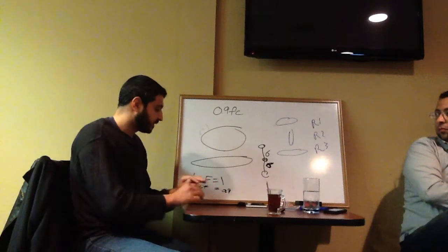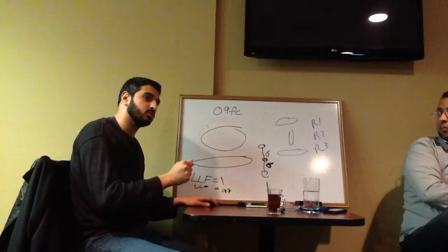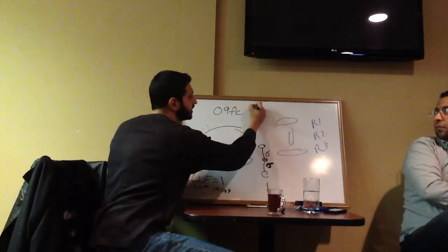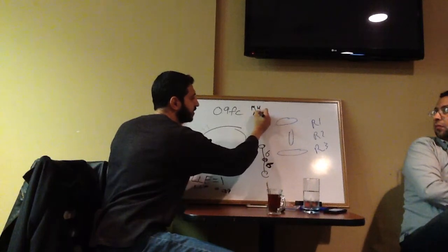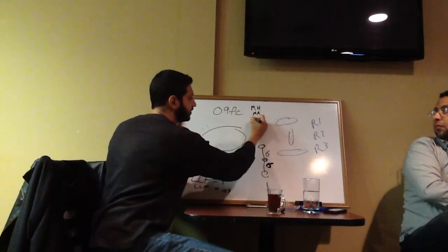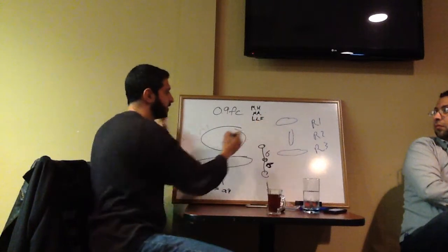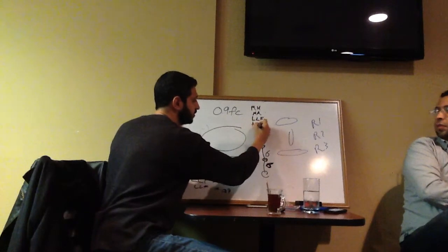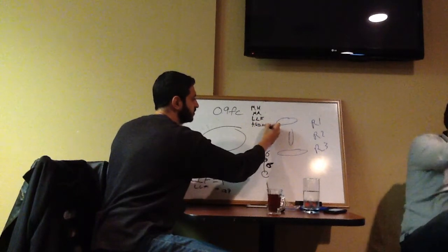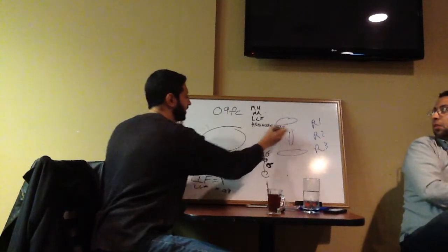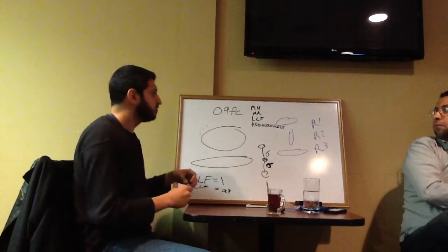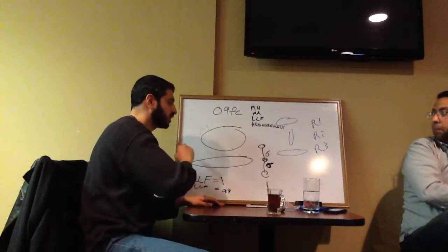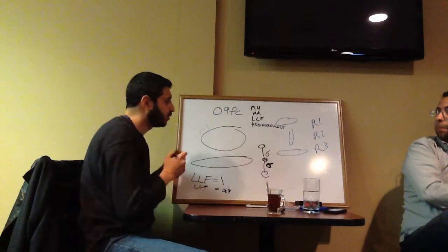Once you put this in, now you're ready to do the calculation. You put in your mast arm length, your mounting height, the light loss factor, and you select the arrangement that you want, meaning one light, two heads. Now you've inputted all the information you need to, you hit OK, and what's going to come up is another table that you have to fill out.